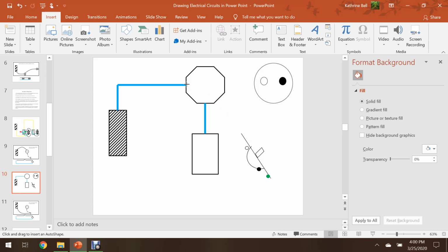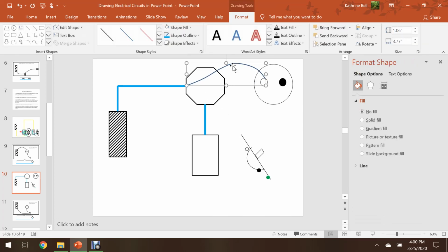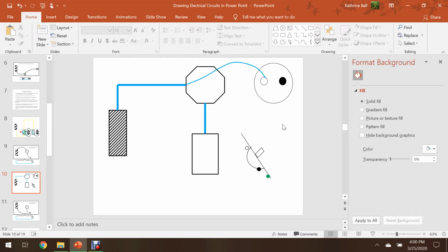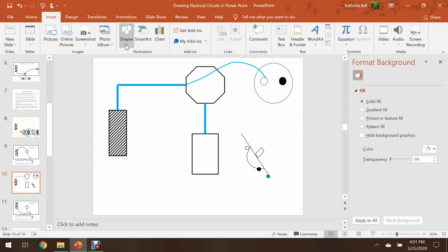So in this case, my white insulated conductor coming from the source is going to go and just connect directly to the silver terminal on the keyless light. That doesn't mean that we don't have a white conductor between the light and the switch. It just means that it's going to be used for a different purpose.